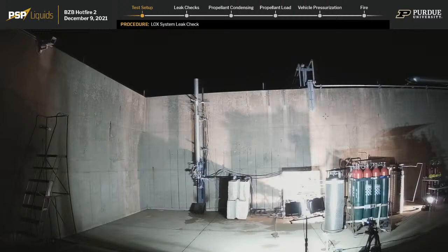What can we do instead to test them in a low energy state, like hydro testing? Yes. So previously to these two hotfire attempts and to our cold flow tests, we performed what was called a hydro-proof test. What we did for that is we filled our propellant tanks with high pressure water and tested them above the pressure that we expect to see in this test today. By testing well above the pressures we intend to see, we have done what's called a proof, or proving that they are safe to use. That makes a lot of sense.